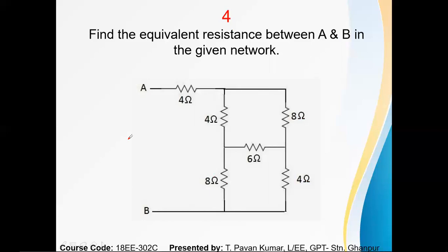Before that, is there any possibility of applying series and parallel in the circuit? If any possibility is there, then we will apply series and parallel before applying star-delta transformations. So first, your job is to apply series and parallel only. Don't go directly to delta and star. That will be a lengthy process, right? Always we use the techniques for saving our time.